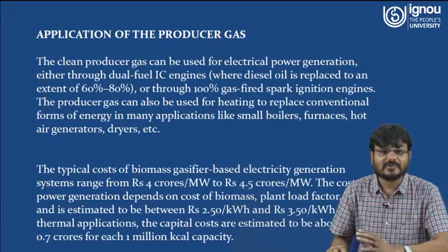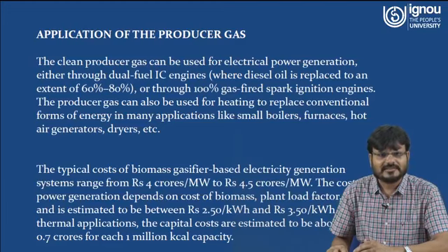The typical cost of a biomass gasifier-based electricity generation system ranges from rupees 4 crore per megawatt to rupees 4.5 crore per megawatt. The cost of power generation depends on the cost of biomass and plant load factor, and is estimated to be between rupees 2.5 per unit and rupees 3.5 per unit.